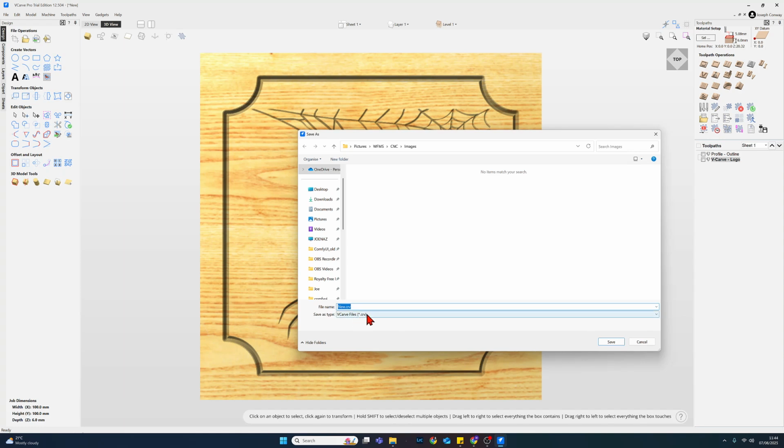And I will take that down to my man shed. We'll load it on the computer that we have there that's connected to our CNC machine, and then open that up on the Makerspace edition of VCarve. And that will allow me then to save my toolpaths. And then with that, I can then point my controller for our CNC to run the job.